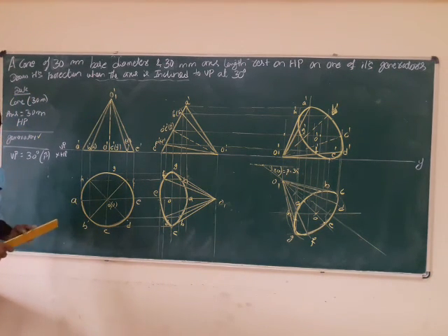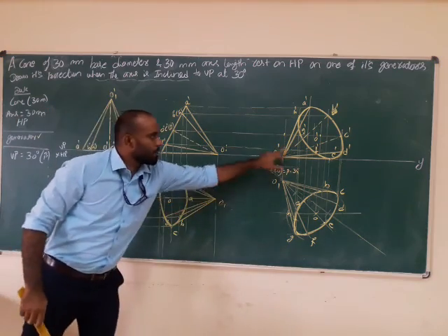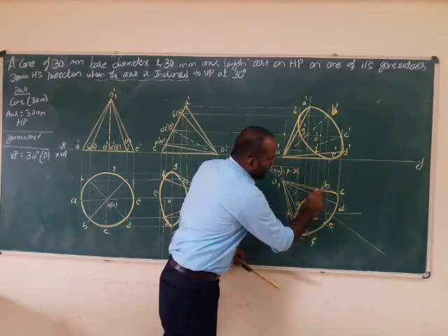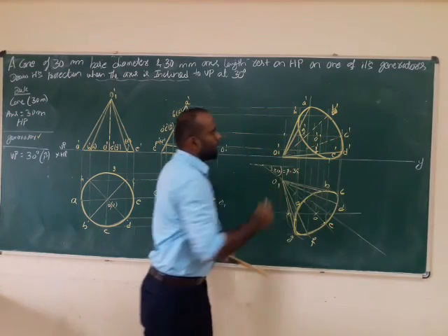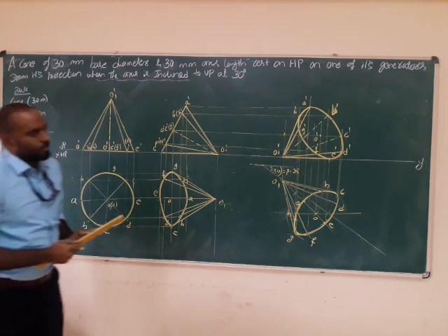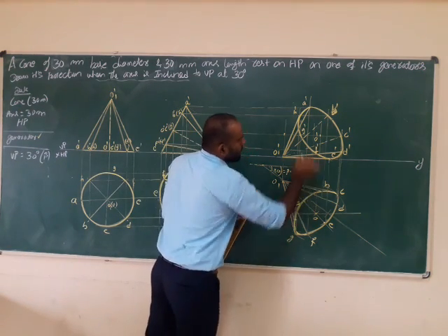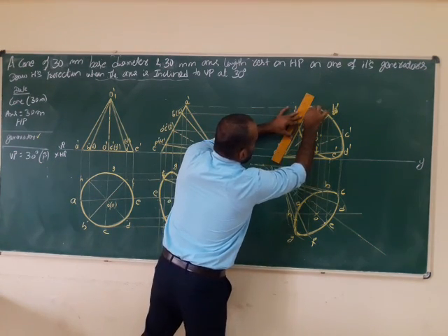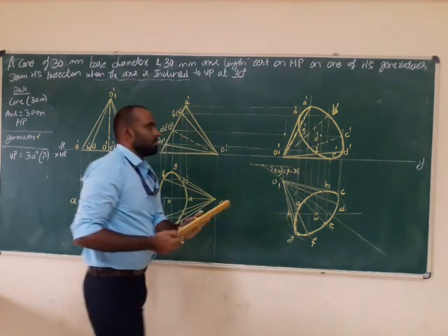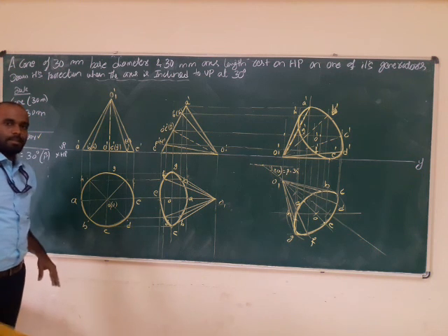This is called the after inclination of beta. You have to find out beta angle. After that, you have to draw line. In bottom view, the B and C are not visible, so that's why you have to draw dotted line. And A is also not visible, so A is also a dotted line. That's it. Thank you.